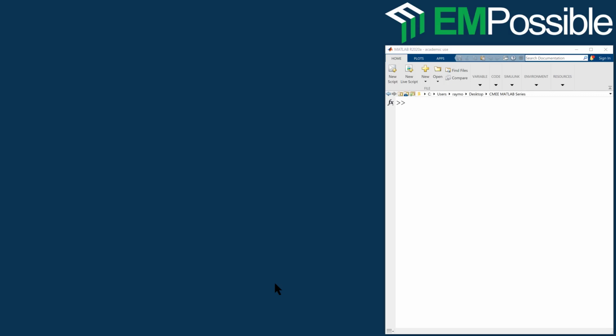Welcome back. In this video, we're going to talk about two-dimensional graphics and how to dress up your two-dimensional plots. For two-dimensional graphics, there are two main commands that we will be using, pcolor and imagesc. And for reasons you'll see, I like to use imagesc a whole lot more. Let's just get right into this.